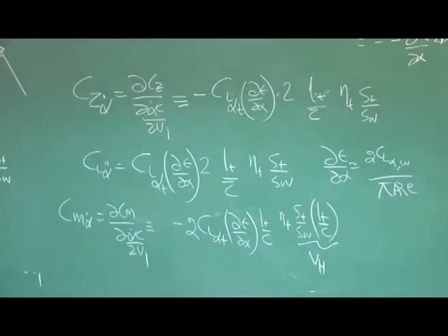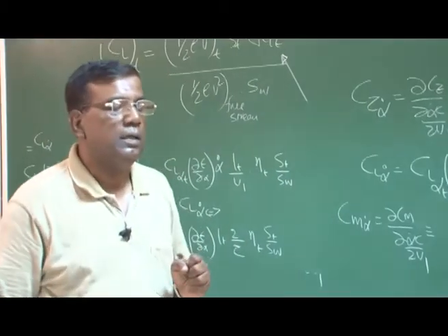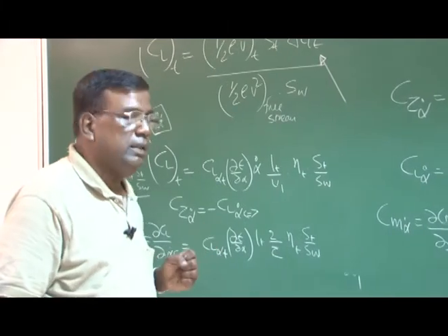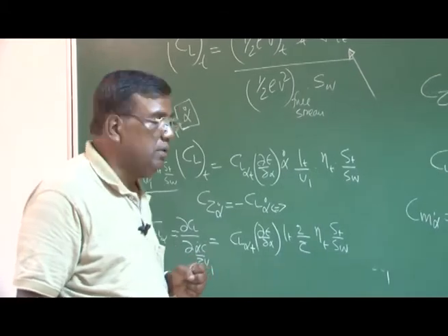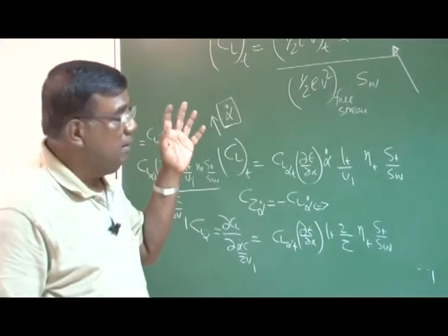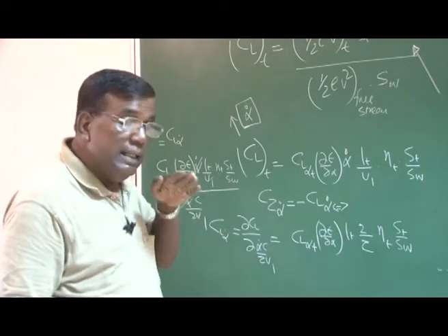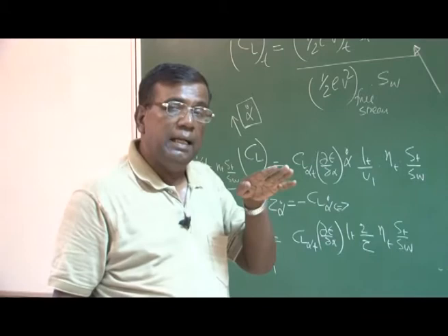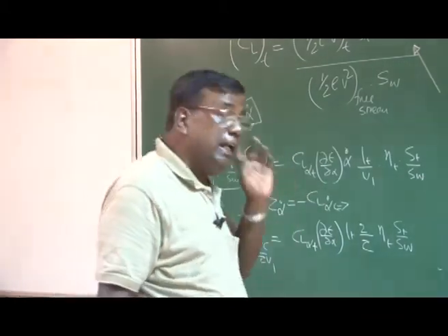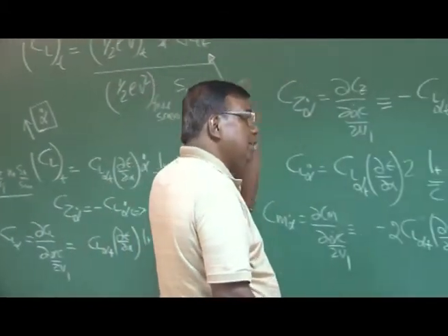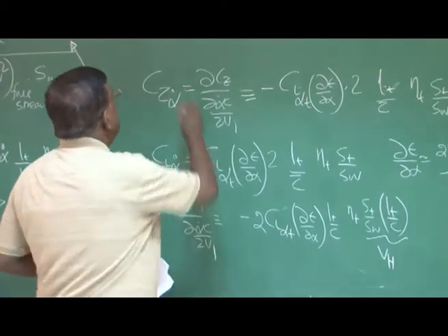That question has to be answered, because we have agreed that whatever we are doing when we are trying to calculate this alpha dot derivative in a downwash lag approach, something has happened at time LT by V earlier. That means, at that time the tail had a larger angle of attack, right, corresponding to that time. So, that larger angle of attack will give a nose down moment or pitch down moment. So, this is the minus sign. Are you clear with it?